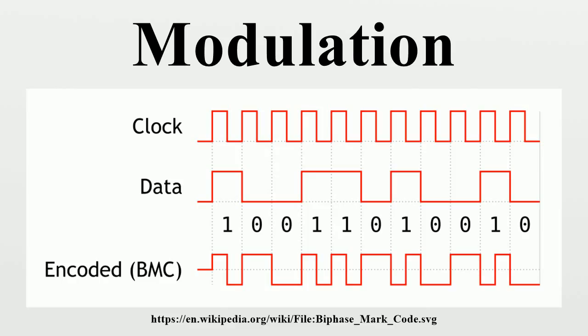A simple example: a telephone line is designed for transferring audible sounds, for example tones, and not digital bits. Computers may however communicate over a telephone line by means of modems, which represent the digital bits by tones, called symbols. If there are 4 alternative symbols, the first symbol may represent the bit sequence 00, the second 01, the third 10 and the fourth 11.